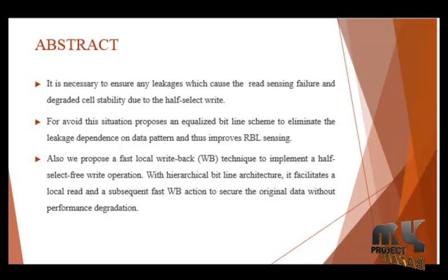So we extend our previously proposed hybrid analytical model for predicting the delay and delay variability of SRAMs. We are designing a 6 transistor SRAM in the Tanner design tool to predict the power and energy variability of a 16nm 6T SRAM under the influence of three major types of variations: fabrication, operation and implementation.